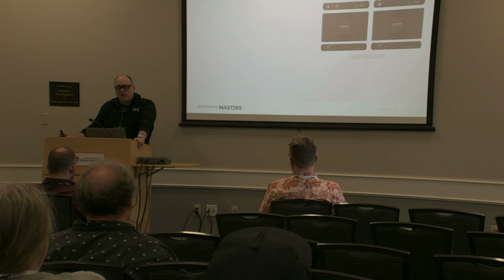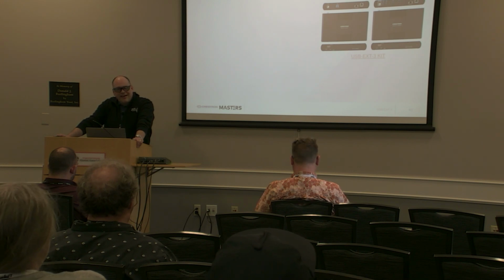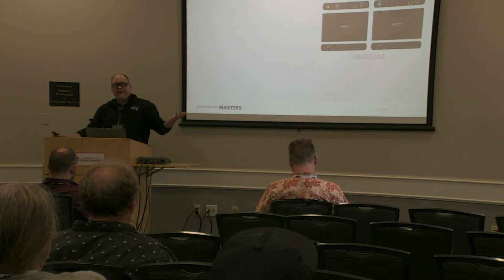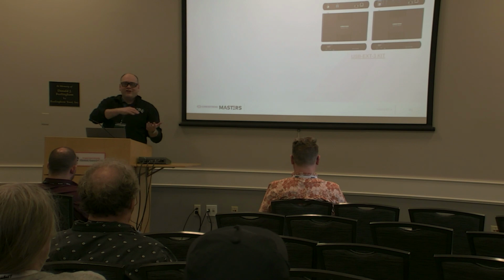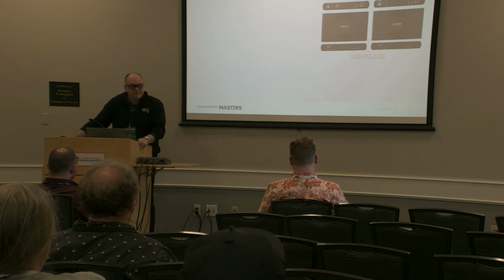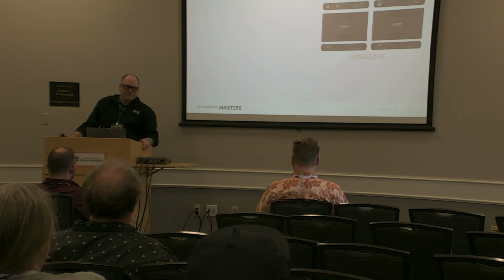They need more power because most USB 3 cameras are the ones with all the processing in them: the framing, the people counting, all that stuff. I think they need USB 3 for the power, not for the video bandwidth. So just something to think about as you're thinking about your design. Also, do you really need a USB 3 camera if you're going to plug into Teams? No, because Teams is going to crush it all down to 720 anyway. Now, will that always be the case? No, but today it is.